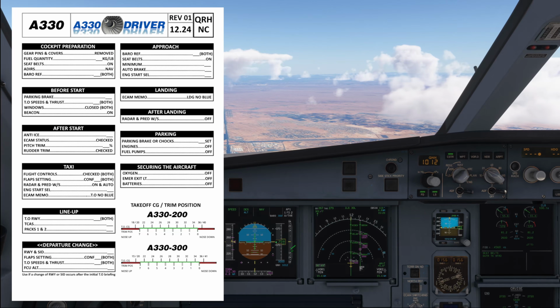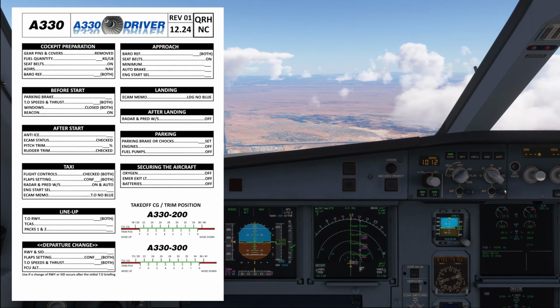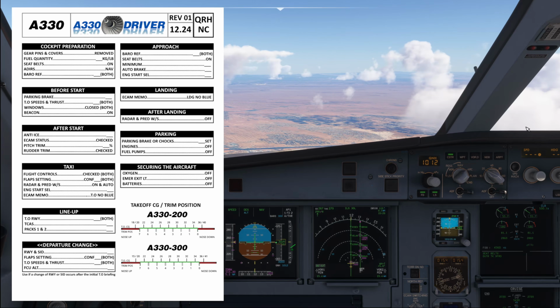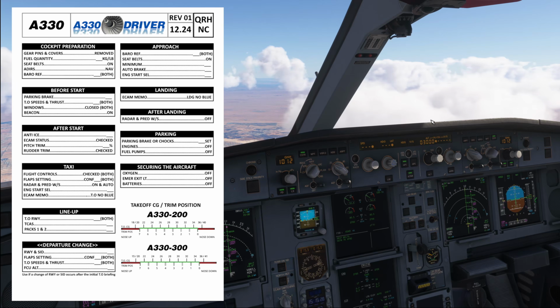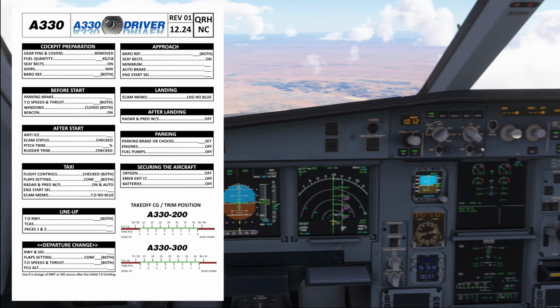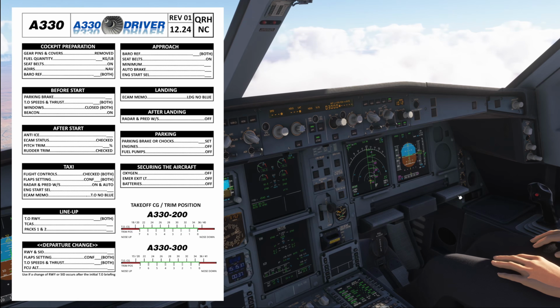We are now below 10,000 feet, and the altimeter has been set to the local barometric reference. Those two are the triggers for the approach checklist. Baro reference, and again the pilot flying and pilot monitoring check and read the QNH baro setting from the primary flight display. So in our case the correct answer is QNH 1012.